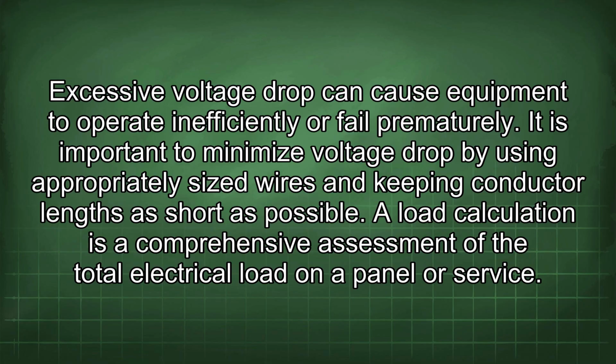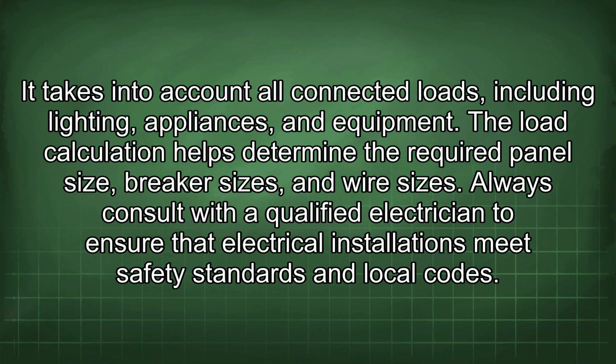A load calculation is a comprehensive assessment of the total electrical load on a panel or service. It takes into account all connected loads, including lighting, appliances, and equipment. The load calculation helps determine the required panel size, breaker sizes, and wire sizes. Always consult with a qualified electrician to ensure that electrical installations meet safety standards and local codes.